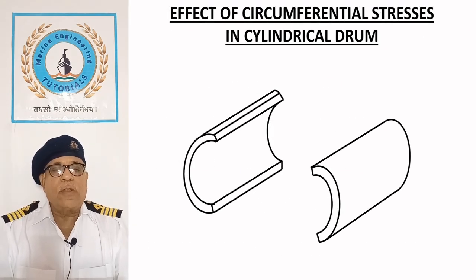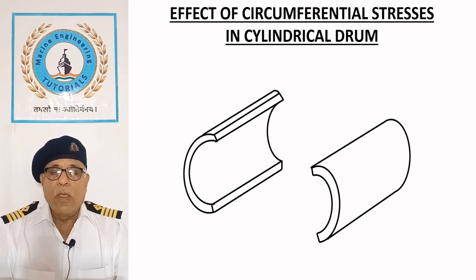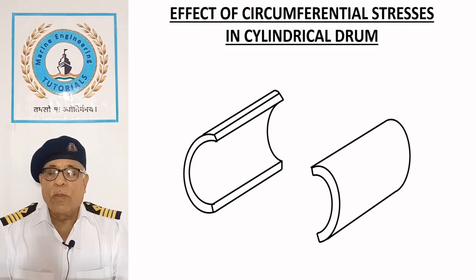Effect of circumferential stresses in cylindrical drum. Various stresses develop in the boiler drum due to the force exerted by steam pressure. A boiler should be designed so that its material can withstand these stresses and serve the intended life of the ship, which is usually around 25 years.